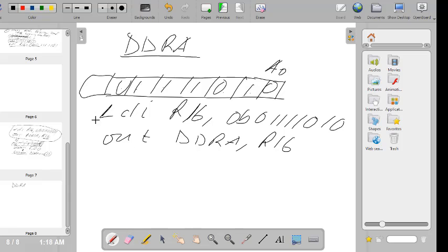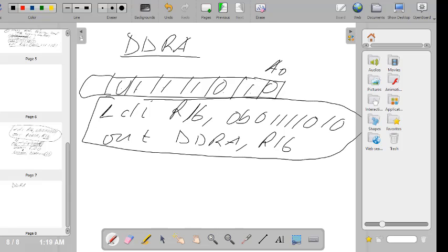Now this simply means that whatever I have done, again moving from right to left, port A0 in this case is going to be configured as an input port. This one will be configured as an output port. This one will be configured as an input port. This one will be configured as what? As an output port, and things like that.